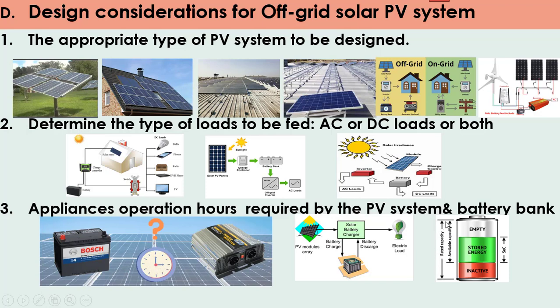The total line represents the rated capacity of the battery, and from the bottom end of the green zone to the top of the battery represents the available capacity that can be used, which represents the depth of discharge for the energy that can be drawn from the battery bank. And this represents the state of charge for the energy stored in the battery.